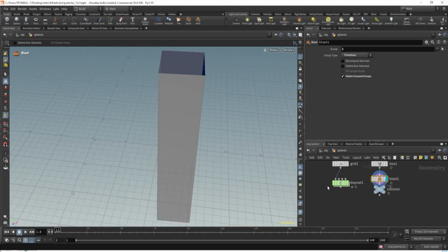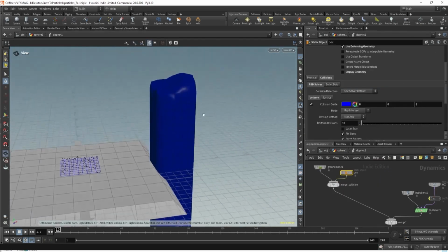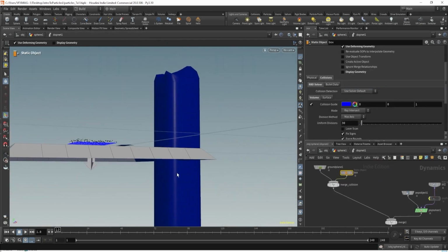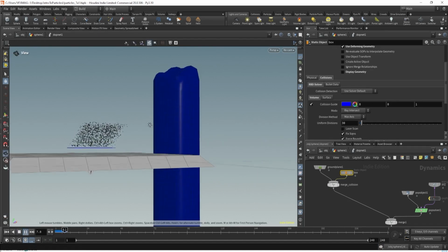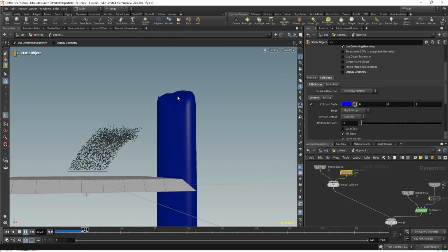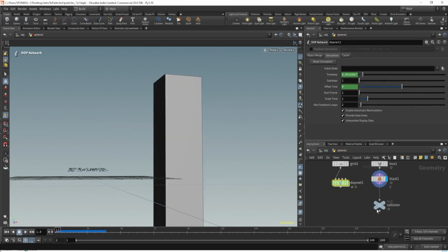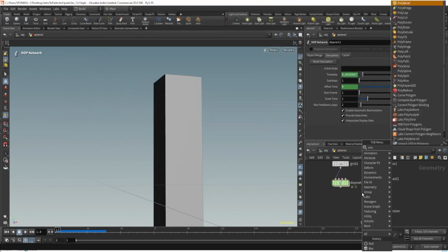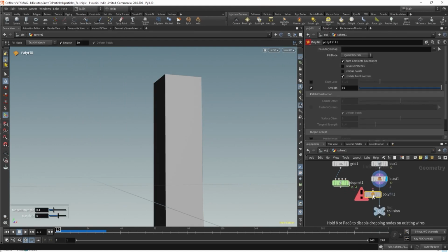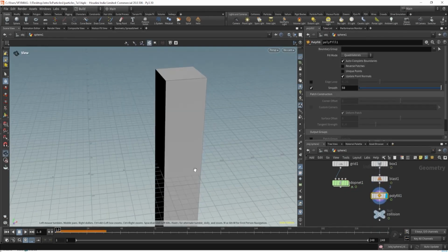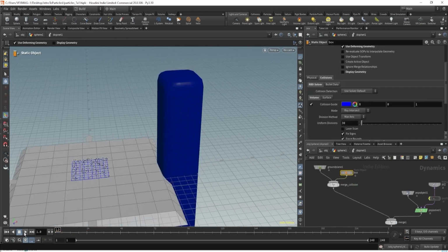Right, so I have this open polygon. You can check this, change the shape also now. Right, see. If you have points over here, it will just bounce. And if you have open polygons, always use polyfill. And make sure you always send a watertight mesh, so you won't have any glitch.